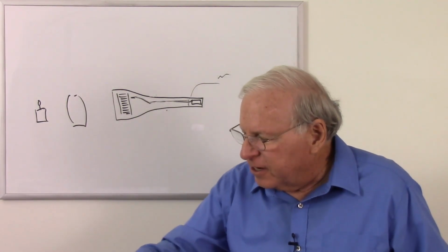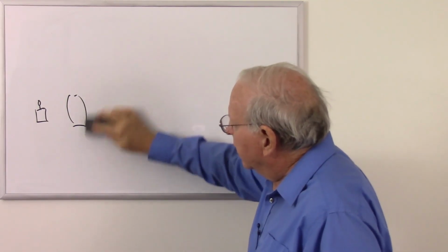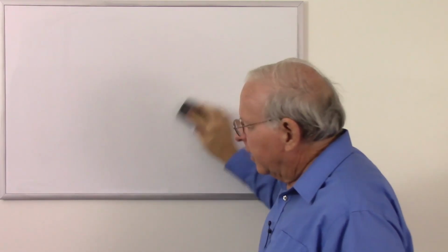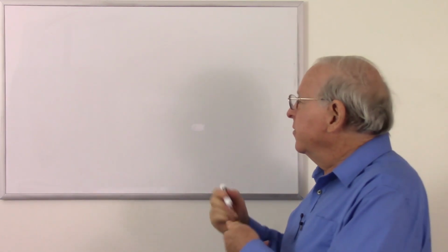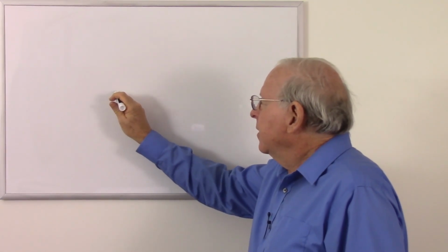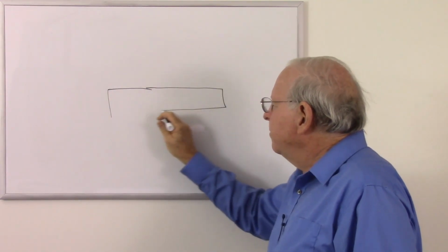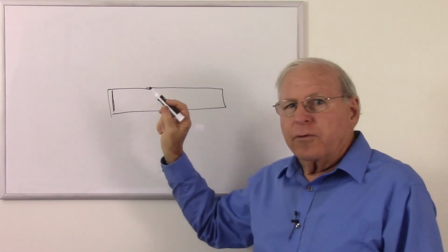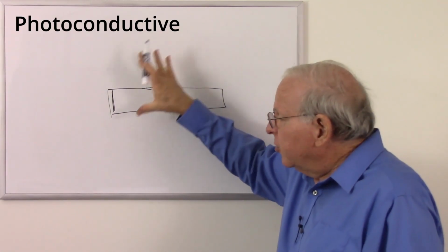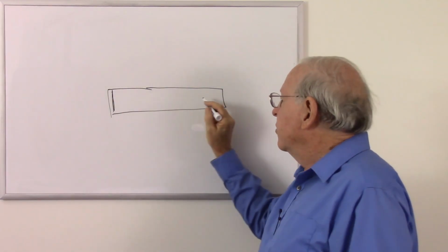And finally, the Vidicon tube, which I'm really surprised wasn't one of the first developed, because when I thought of how I would make a picture camera, that was the first thing I thought of. So we have a tube. Ones I've seen were pretty tubular. Here is a screen that is photoresistive material. In other words, in the dark, it's a high resistance. When light strikes it, it's a low resistance.